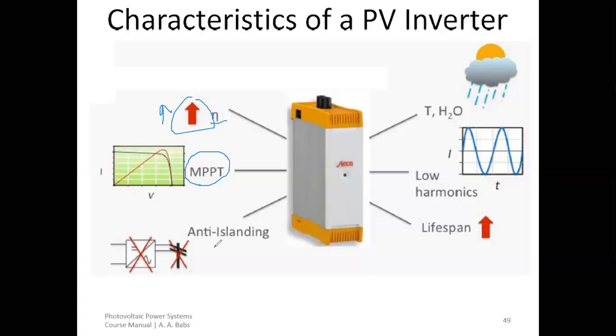So when electric grid power is no longer present, the DC generator continues to power a particular location, and this is dangerous because workers, once there is no electric grid, will assume that there is no power. So if care is not taken, the DC generator will continue to power the location, and those workers might be in danger. It's very unsafe for workers and the entire environment.